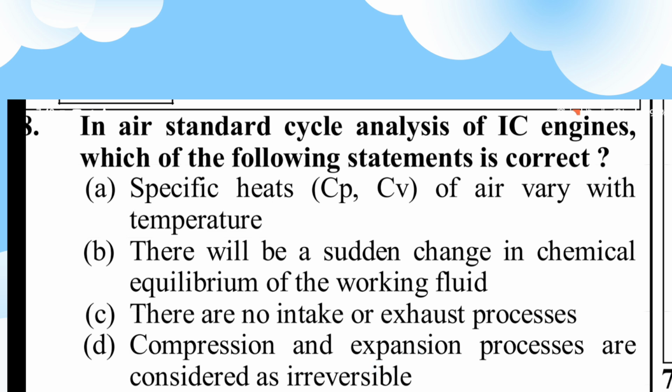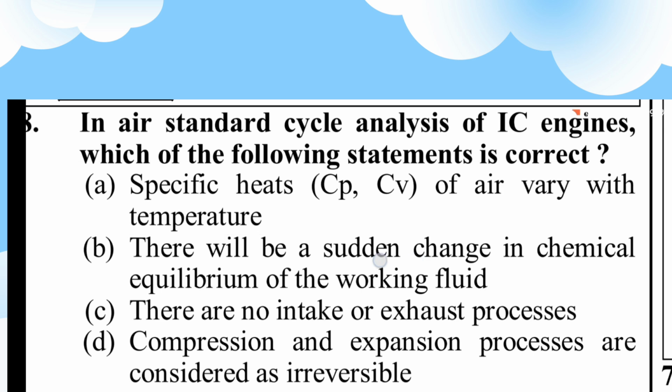Question number 68. In air standard cycle analysis of the IC engines, which of the following statements is correct? A. Specific heat Cv of air varies with the temperature. B. There will be a sudden change in the chemical equilibrium of the working fluid. C. There is no intake or exhaust process. D. Compression and expansion processes are considered as irreversible. C, there is no intake and exhaust process.